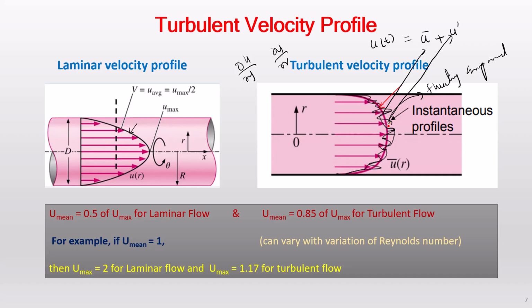So that is one approximation that you get in CFD. There is the truncation error, that is a mesh error, where you are leaving the high order derivative terms in your equations, and also you have the finite size of the cells. It cannot go to zero. And the second error is coming from turbulence. So whenever you solve through RANS, you can expect an error ranging maybe from 5 to 15%. I always try to keep the error less than 10%, but sometimes it may be higher depending on the flow nature.